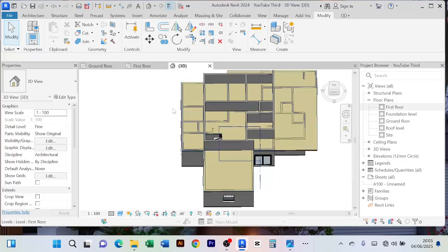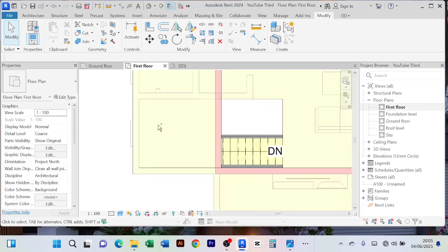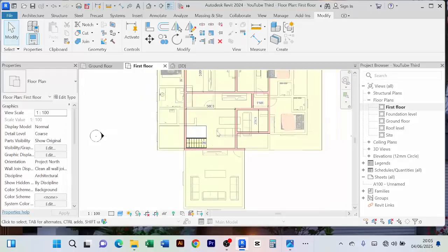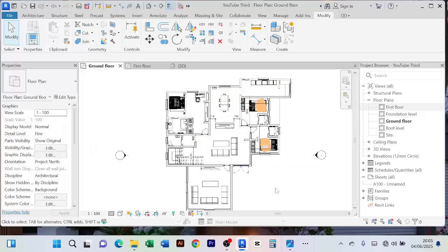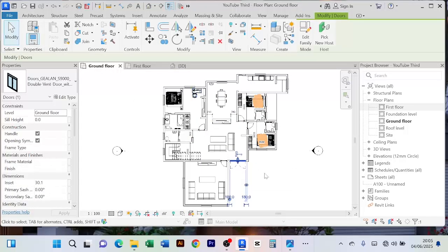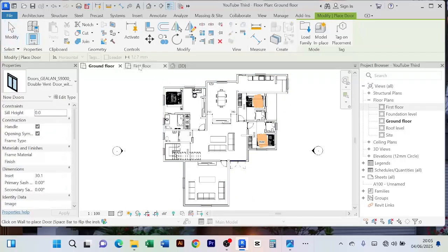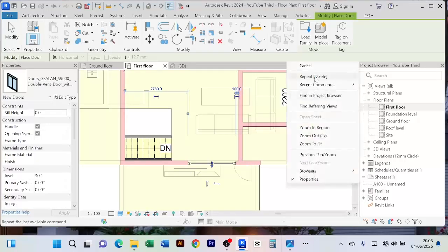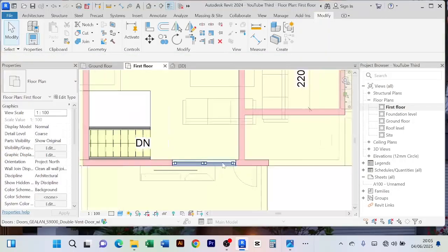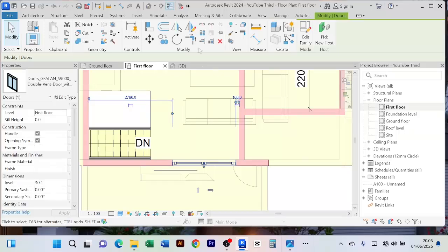So now let's furnish our room. Let's start furnishing these rooms. So we shall start by putting doors and windows. So let's go to the ground floor. We pick a door here, this common exterior door. This time you just come to create similar. You go to your floor, the other floor, you can put it here. Then I'll place another one. I think this side we shall need a single door, so I'll place it here.